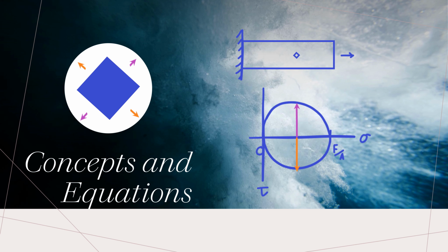Right here we have our maximum shear, and we have equal magnitudes for my sigma x and y. And when we have max shear, that means we rotated 45 degrees, but on a Mohr circle we have to rotate 90. So this is just a general rule of how it works. And then last, here's kind of an arbitrary location.